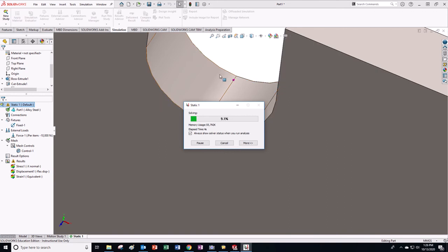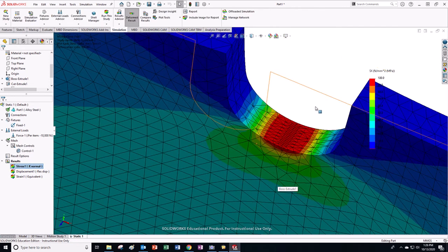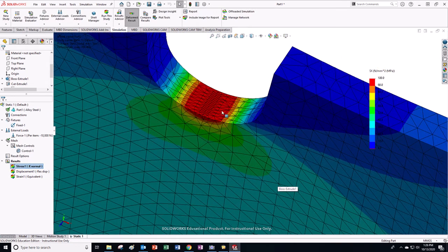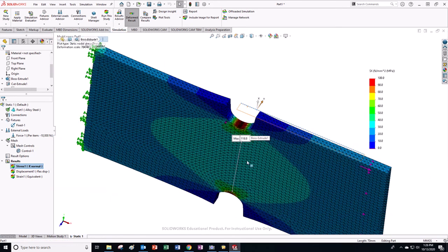It's much more efficient to make localized stress elements along those lines. But there still can be some effect, so we might want to explore how much further out we might go. So what is the maximum here? Now the maximum is 118. I still get 118.